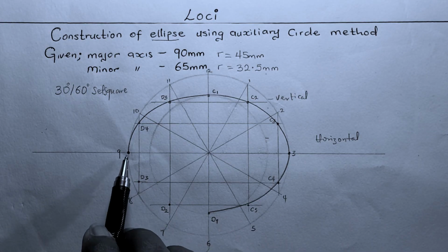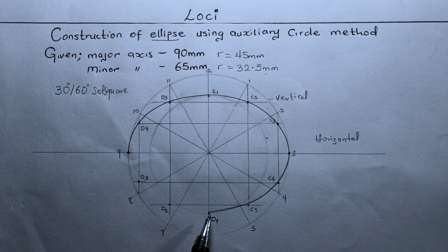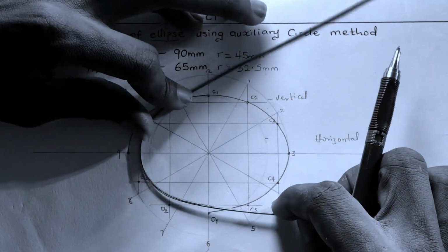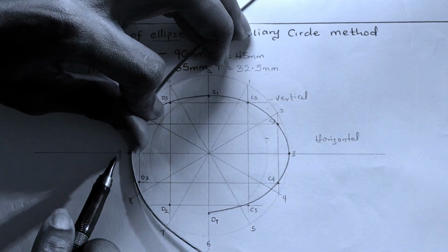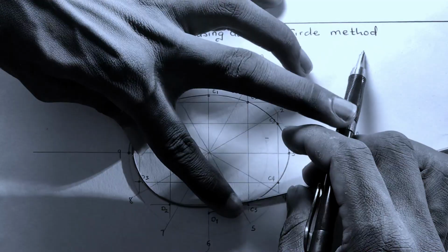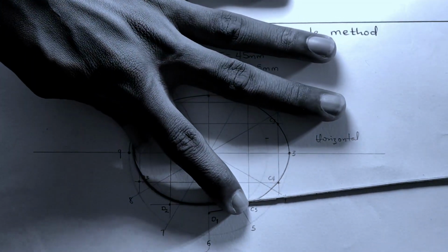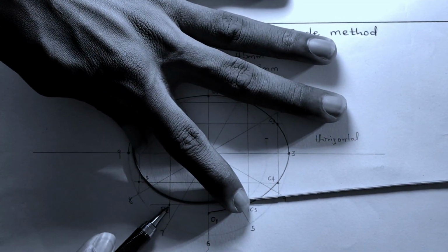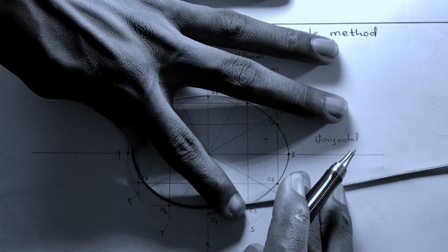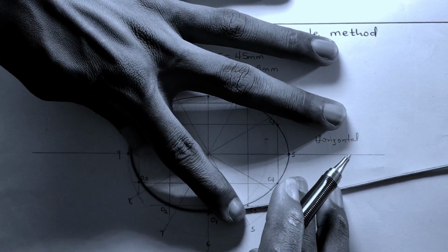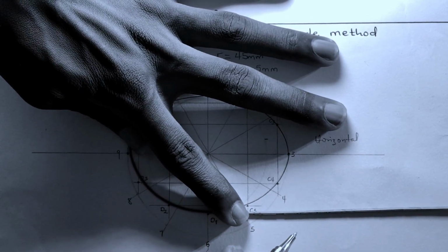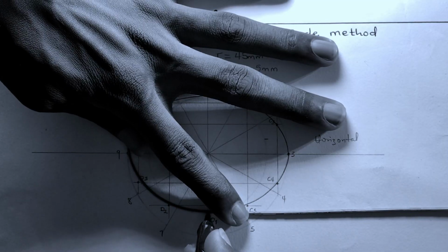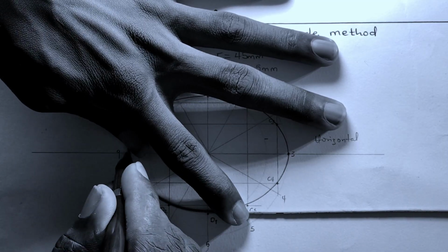And then to the last side of the ellipse. So we have this point, we have D3, D2 and D1. So to join those 3 points together, we set our broomstick at point 9 and ensure that it touches the other points, which are D3, D2 and D1. So with that we are going to draw the fourth quadrant to complete our ellipse.